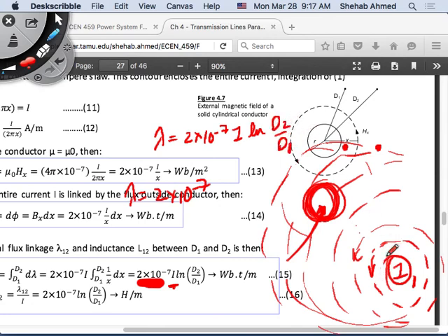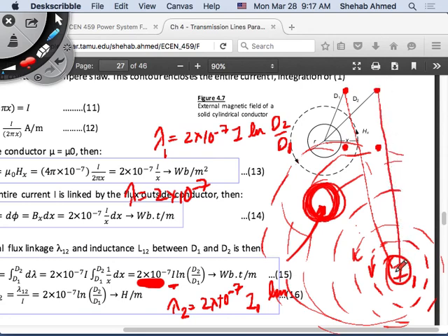How about for this conductor? Also, what I would like to know is the effect of the magnetic field, or the flux linking points 1 and 2, right? I would like to find out what the magnetic field is linking these 2 points. So this is going to equal to what? 2 times 10 to the minus 7, I1, natural log what? Not d2 and d1 anymore. d2 and d1 were for this conductor.